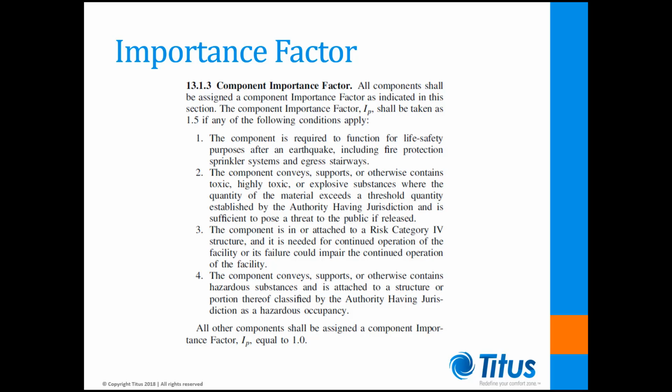Next, a component importance factor must be assigned. For non-structural components like HVAC equipment, this value can be either a 1.0 for least importance or 1.5 for highest importance. Guidelines to the importance factor determinations can be found in Section 13.1.3 of ASCE Section 7. The final piece of information required is the mounting method and weight of the equipment.